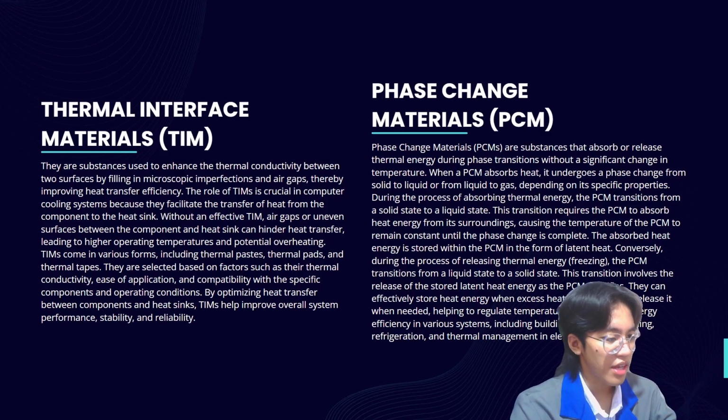The role of TIMs is crucial in computer cooling systems because they facilitate the transfer of heat from the component to the heatsink. Without an effective TIM, air gaps or uneven surfaces between the components and the heatsink can hinder heat transfer, leading to higher operating temperatures and a potential risk of overheating.